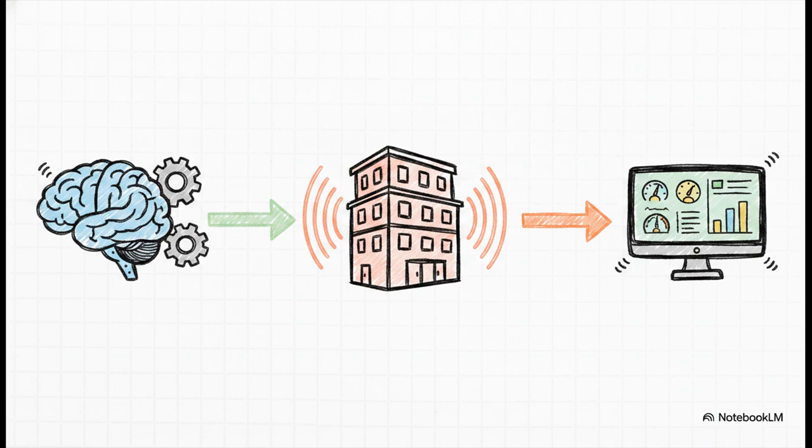Actually, scratch that. You rarely do. Python scripts running inside your twin can automatically trigger trusted commercial third-party software like ABAQUS or MATLAB to just run complex structural analyses quietly in the background. In the DTOP-Cristallo project, for example, they use this exact method to test the natural frequencies of a 3-story physical structure and then funnel the results right back to the user's dashboard automatically.